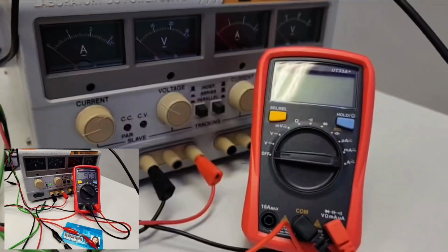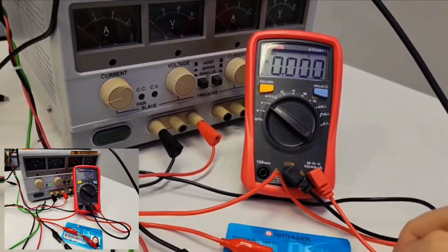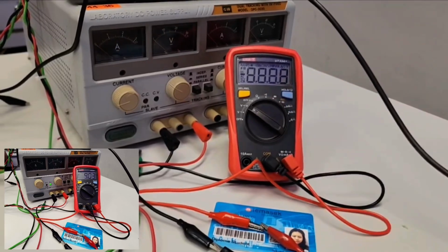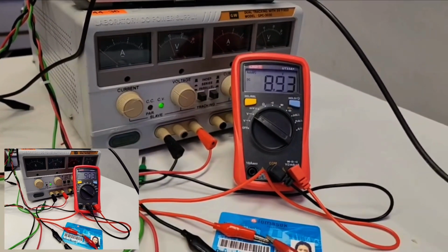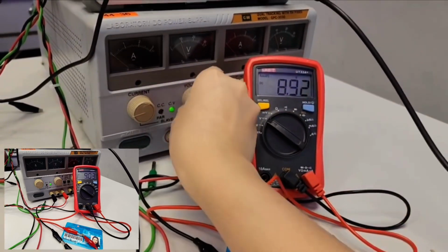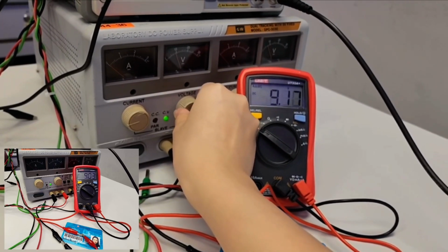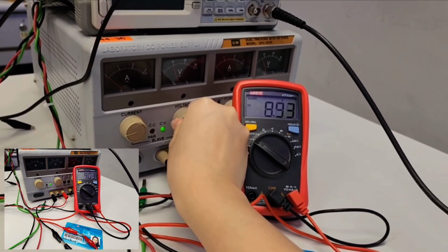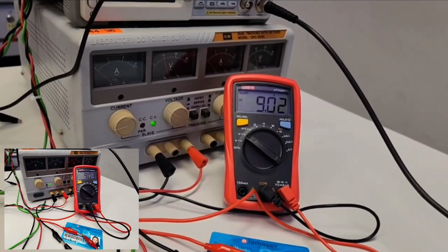Before we start looking into the results table for the amplifier at stage 1, I will walk you through how I start circuit testing. The DC supply voltage for testing should be 9 volts, so I connected the positive terminal and the negative terminal. I ensure that I set my DMM to measure DC voltage. I set the DC supply to independent mode, put the current knob horizontally to the left, and adjusted my voltage until the DMM showed about 9 volts.